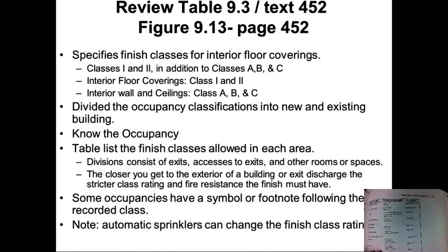So you can see, going down through here, you've got to be able to know what these are. Mattress tests, commercial applications, or all applications. You've got to know. It specifies finish classes for interior floor coverings, class 1 and 2, and interior wall and ceilings, classes A, B, and C.